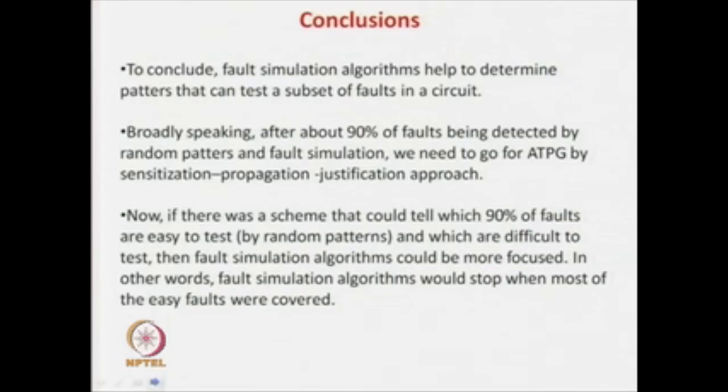So, that was about fault simulation. To conclude, concurrent fault simulation helps in random test pattern generation. We apply some random patterns and then find out which faults can be detected by them. You can use serial, which is the slowest one. If your computer supports a lot of parallelism, you can go for parallel fault simulation. Otherwise, you can go for deductive fault simulation or concurrent fault simulation.